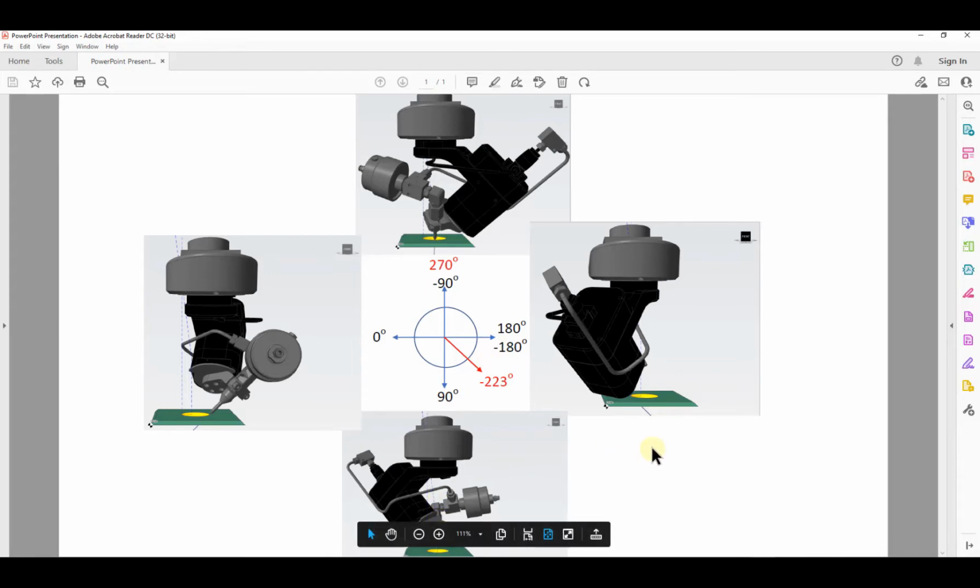And if the cutting head or the stream is coming straight towards the front of the tank, then that corresponds with being 90 degrees. And if it's pointing straight back, then that's either negative 90 or 270. Generally, you're going to want to try to position your lead such that you're pointing towards either positive 180 or negative 180, and then adjust the direction of travel such that you avoid the limits.